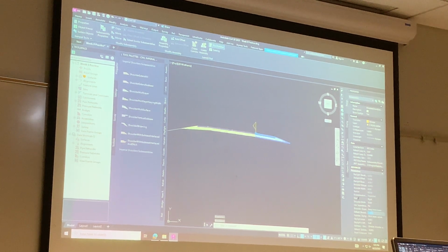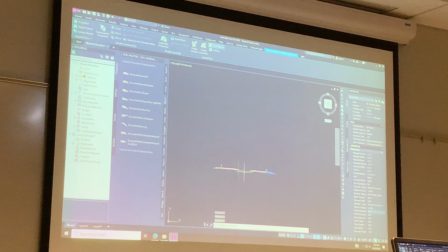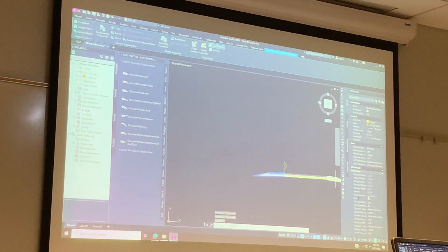And the shoulder and subbase slopes are -5, not -6. What are those called? Shoulder extend subbase. It's on the shoulder tab. Oh, yeah.